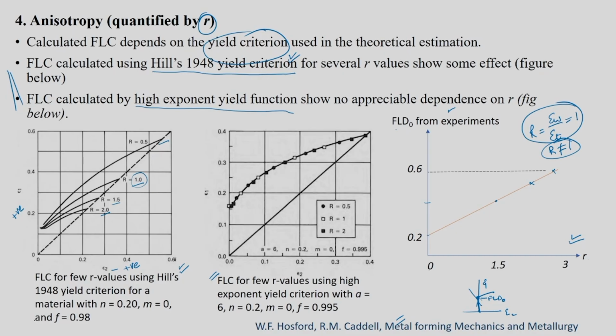Okay, so there is a large difference in your limit strain value when you go for the 45-degree line, let us say balanced biaxial stretching like this. Large difference: 1, 2, 3, 4. These points have a large difference in forming limit. But if you go closer to plane strain in this direction, you will see the window actually reduces. The difference is actually little between these.